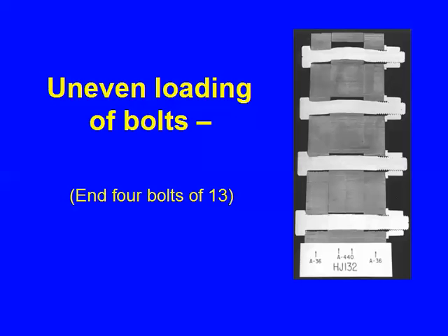It means that the shear load carried by the top bolt is a heck of a lot more in this illustration than is carried by the 4th bolt down. We cannot take the total load and divide by 13 to get it. We can get an average, but it won't be valid. It's just too far out. Now this has been set up so that the imbalance or the deviation from average is pretty high. But nevertheless, it's true, and the specification has to take that into account.